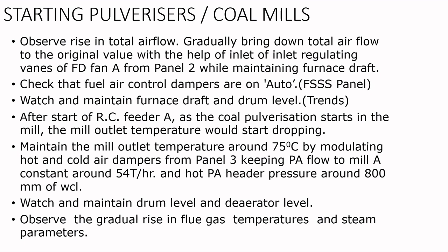The hot PA header pressure is also on auto. Now watch and maintain the drum level and the deaerator level. You can see in the trends and control the drum level by means of operating the valves or maybe the scoop of the BFPs. Now observe a gradual rise in flue gas temperatures and steam parameters, that you should observe.